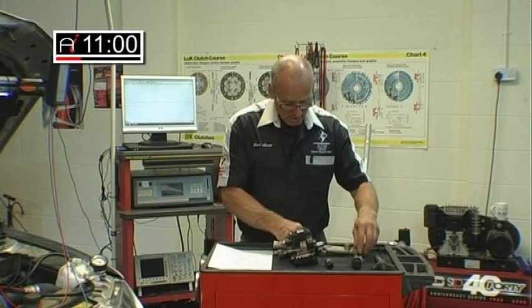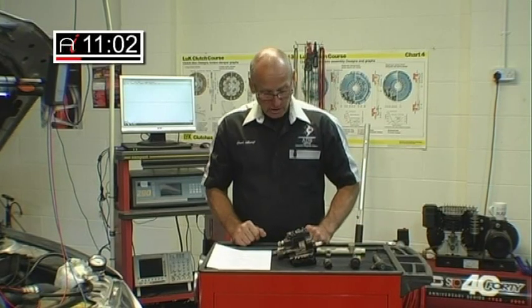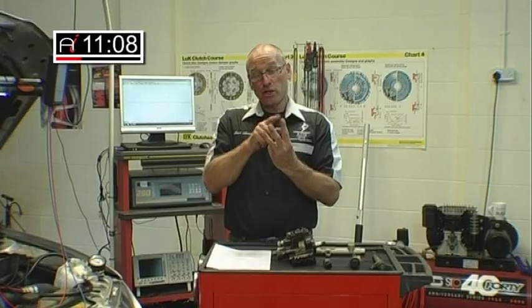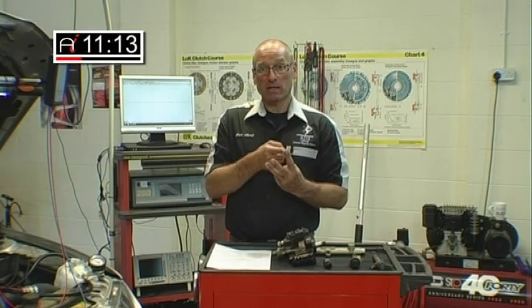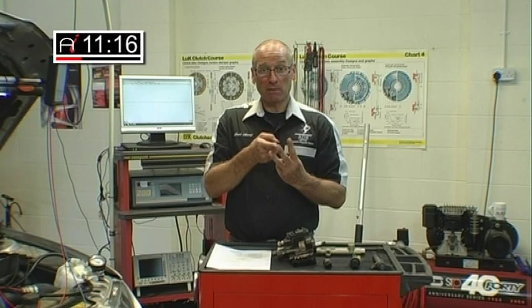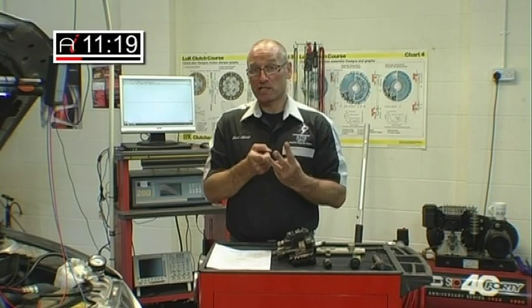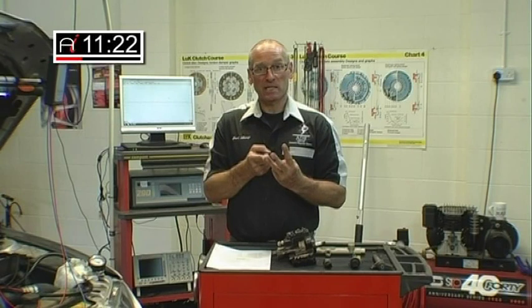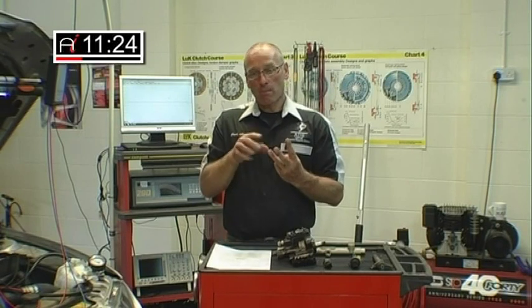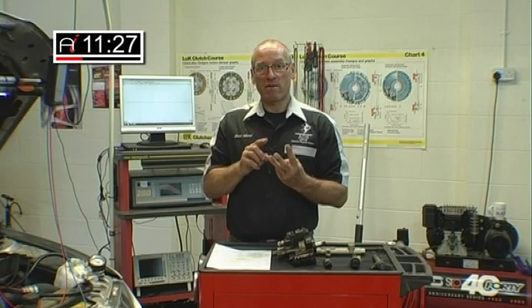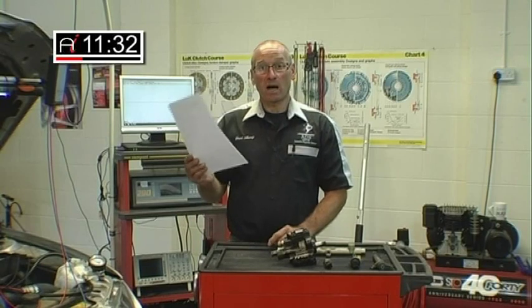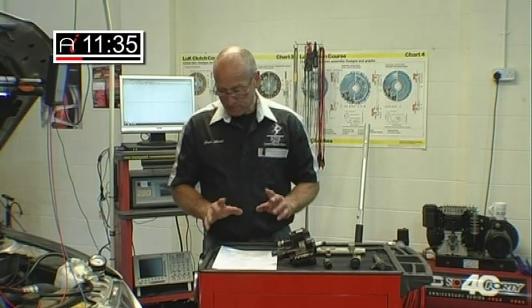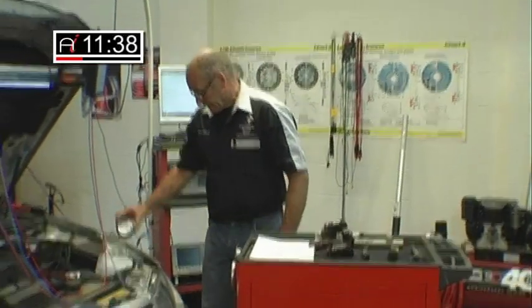But I think first of all, let's take a look at priming. Storage and priming, pressure generation, fuel delivery. In the correct order, given the faults that we have, always make sure priming is correct before attempting to blame the high pressure pump or potential leakage across the injectors. At the moment, we don't know where the fault is, but we're going to establish a method to direct us to the cause, not the symptoms. What we're looking at here are symptoms. So the first port of call is priming pressure.